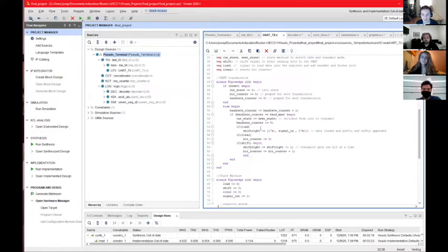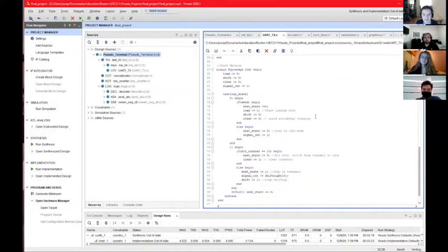We also have some other functions built in to load things and clear things, but the shift of the register to the right is the main function that transmits the data. And then we have the state machine that really just alternates between idle and transmitting, and it stays at a steady 1 for its idle state, and then when it receives a 0 to drop low, that indicates that it starts a transmission of 1 byte of data.